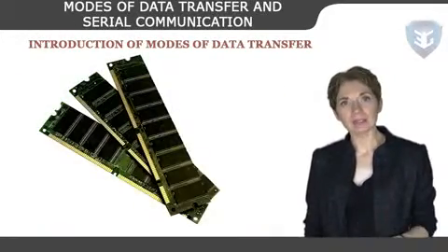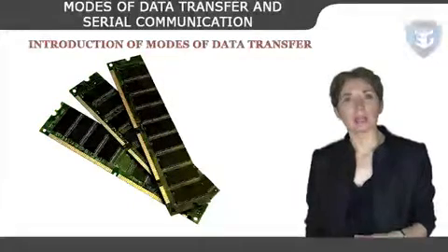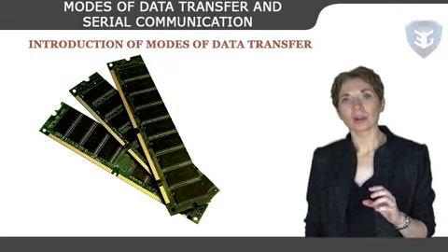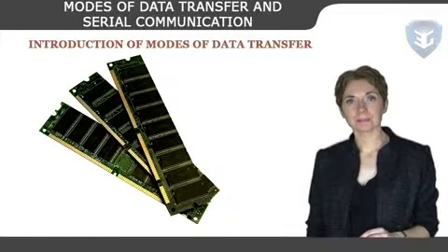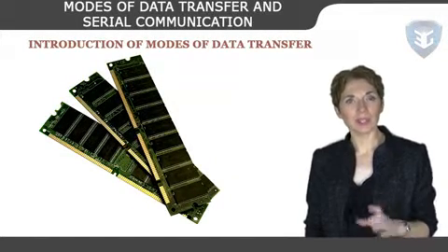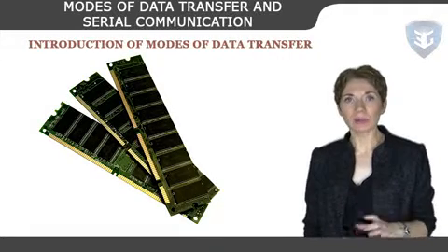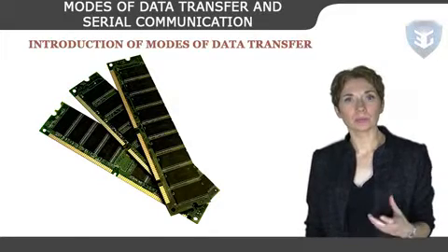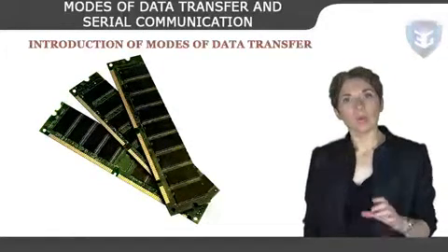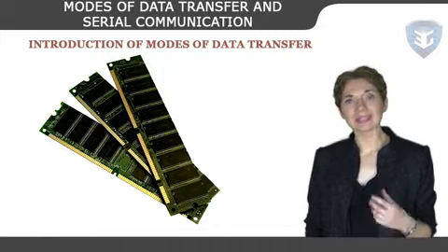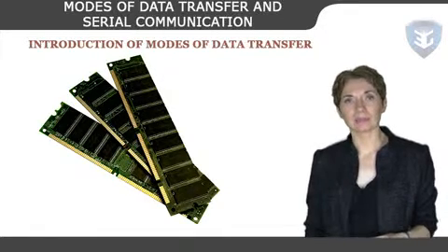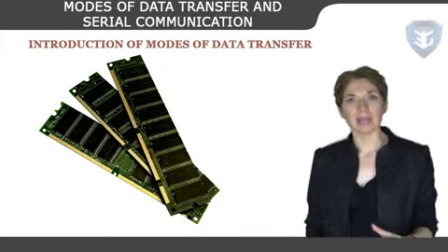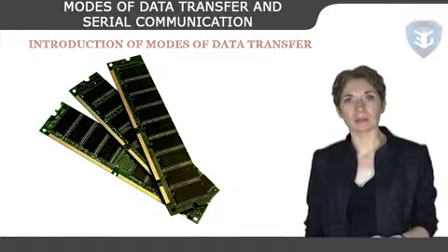The CPU activates the bus grant, or BG, output to inform the external DMA that the buses are in the high impedance state. The DMA that originated the bus request can now take control of the buses to conduct memory transfers without processor intervention. When the DMA terminates the transfer, it disables the bus request line. The CPU disables the bus grant, takes control of the buses, and returns to its normal operation.